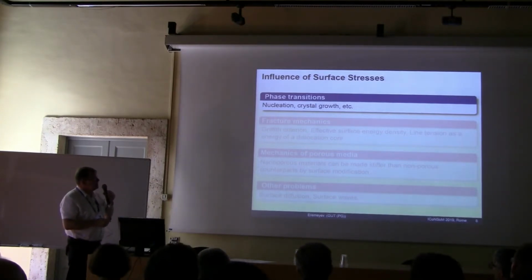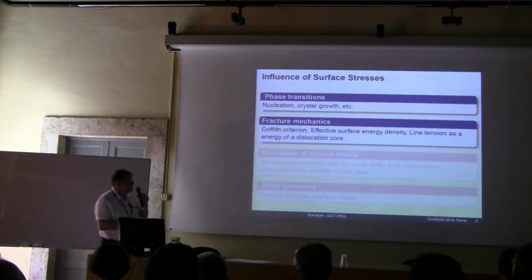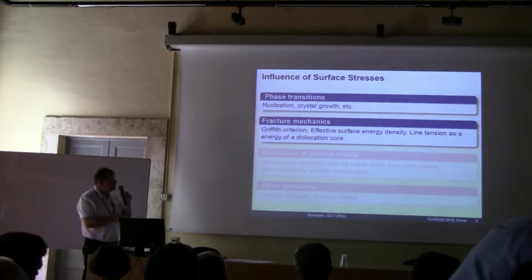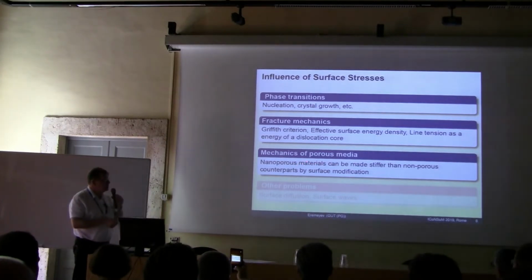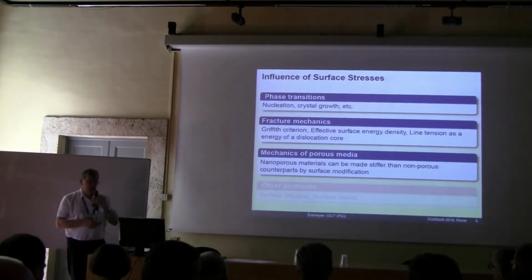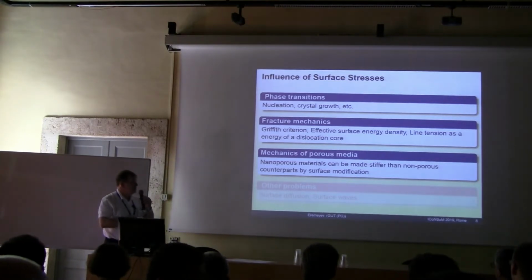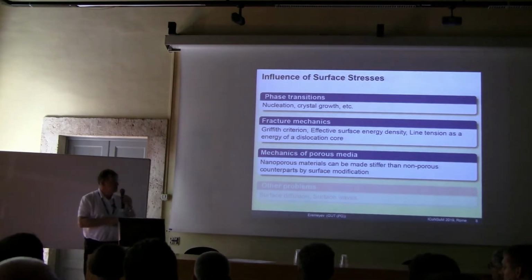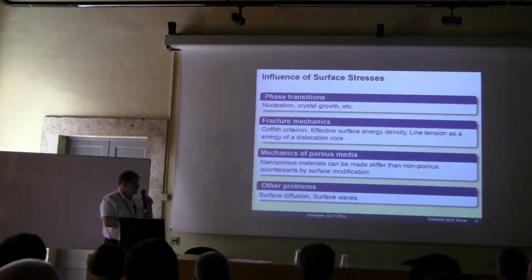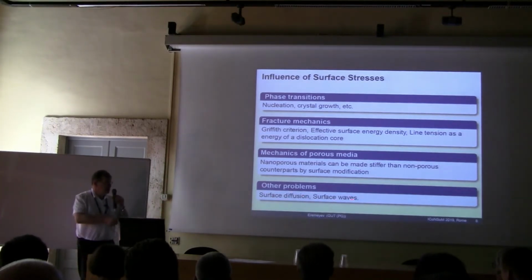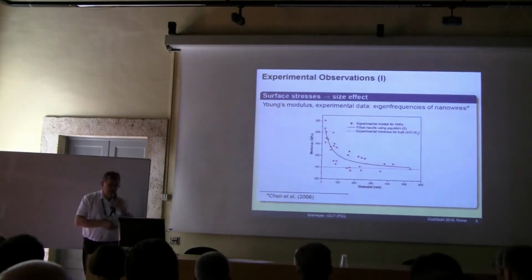Typical examples include phase transition, the problem of nucleation, and fracture mechanics, for example Griffith's energy, line tension energy, and energy in the dislocation core. Of course, surface phenomena are quite important for porous materials, for any materials with a very developed surface, where the number of particles lying near the surface is comparable with the particles in the bulk. Other properties include surface waves, surface diffusion, and capillarity. Surface tension is responsible for so-called capillary waves in hydrodynamics.